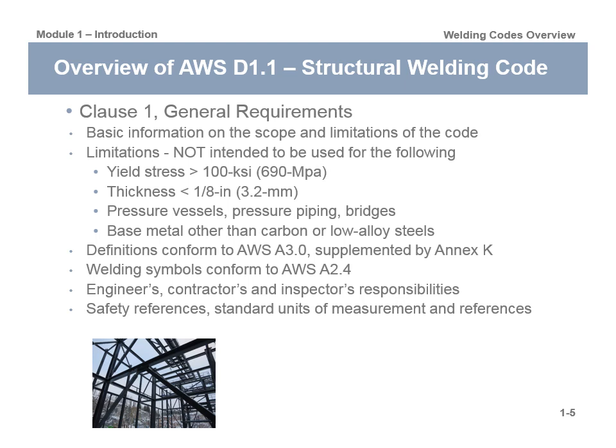I've had instances in the past where I had to explain to an engineer that they wanted something built to AWS D1.1 like a hydraulic cylinder, and I'm like, hydraulic cylinders don't fall under AWS D1.1. Well, it's the welding code. No, it's a welding code for structural steel. That's it. Structural steel, buildings.